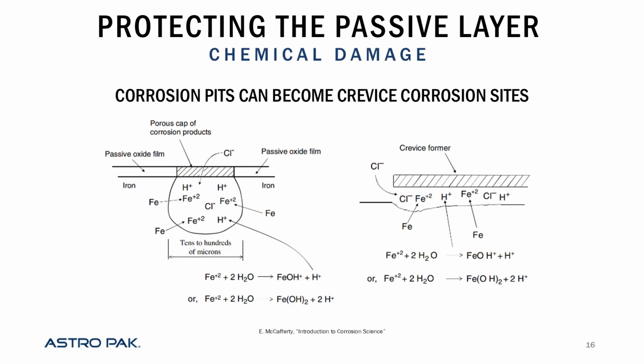A major takeaway I want to talk about here: it is the chloride, the chlorine ion, that is drilling through the passive layer. So that is the chemical attack that is exposing our 65 to 70% iron in the base metal. All ions of chlorine are corrosive to an extent on stainless steel. So this is the chloride, Cl-, hypochlorite, ClO-, chlorite, chlorate, perchlorate. All 5 of those ions are corrosive to stainless steel at varying thresholds though.